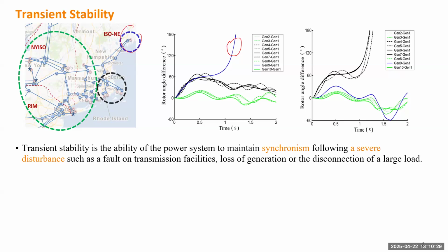So if you have some disturbance near that group, that can make that power plant fly away, right? But the remaining system, even if it forms two coherent groups, they still stay pretty close. So the rest of the system is still stable, but this generator will be tripped. So this is one scenario of a single generator losing transient stability.